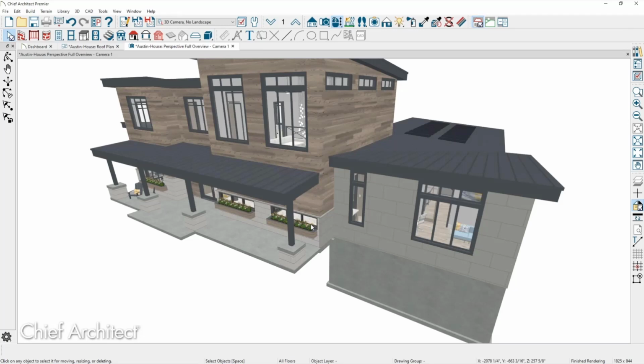And when I did that, my default overhang was 20 some inches, I believe. And it wrapped around here. And as a result of that, this sidewall off to the side, when I changed the invisible wall to be a full gable wall to make this porch have a shed roof, well, this still had a bit of a cricket in it or a hip roof.